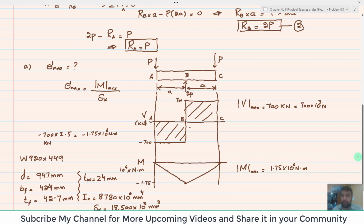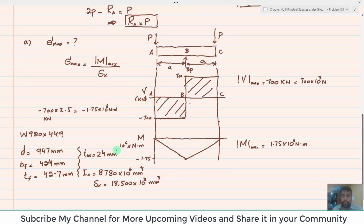Now you have these values, you can put them in this formula, that is maximum bending stress is equal to moment, and this moment is 1.75 into 10 raised to power 6 Newton meter, divided by section modulus, which is 18,500 into 10 raised to power 3.